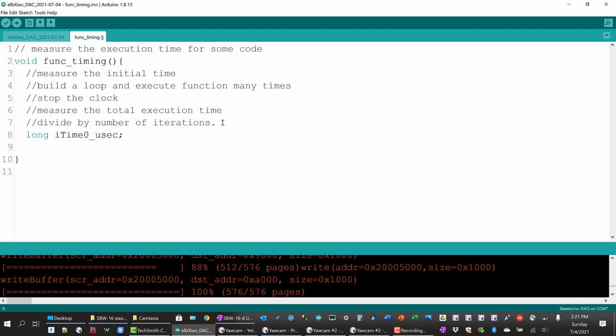Then we're going to do a digital write. And we're going to see how fast we can toggle digital write on, off, on, off. So we're going to do that 1,000 times. So here's our loop. We're going to do a for, and here's our index that we're going to move, starting at 1, and we want to keep going with the loop until the index reaches 1,000.